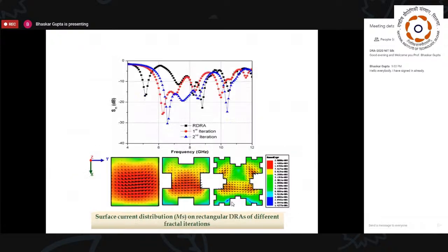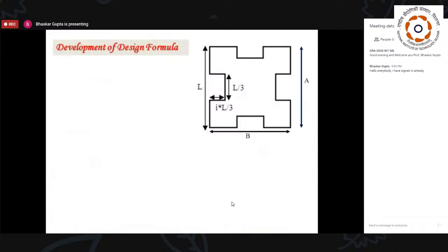And also here, because of dielectric nature, we would expect some magnetic current. Of course, that's hypothetical, just to model a slot, and that magnetic current distribution can be plotted like this. Similar observation can be made from here also. Look at this S11 plot. So that actually serves our purpose. That way only we can get our broadband antenna using this Minkowski island fractal.